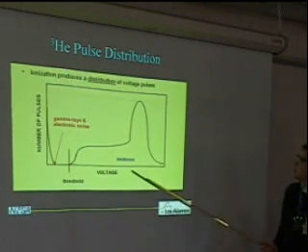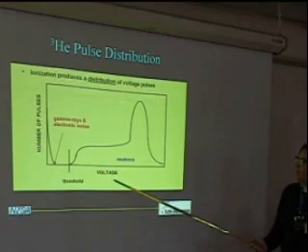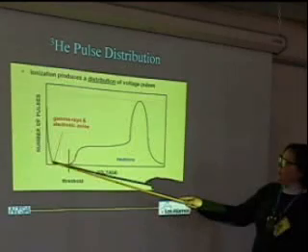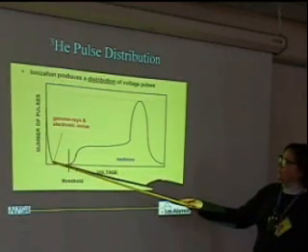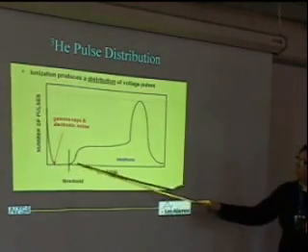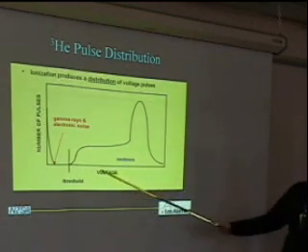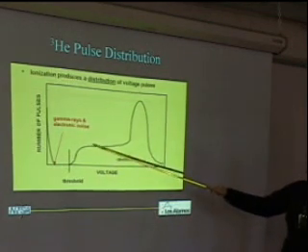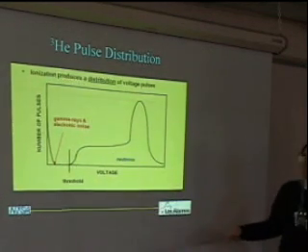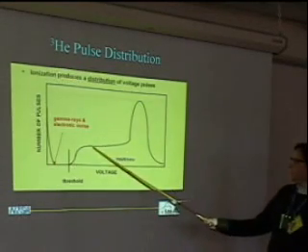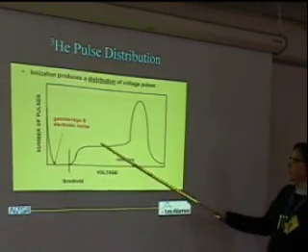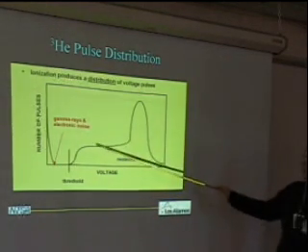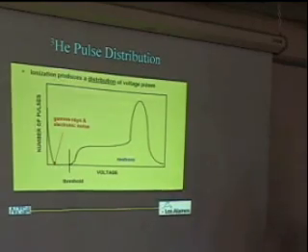If this is the distribution of the voltage pulses coming out of a helium-3 tube, the gamma rays and electronic noise have very low magnitude, and then depending on where you're running the high voltage of your detectors, you can see there's a plateau region here where the neutrons have saturated the cascade, and so you want to operate your detector in this region.